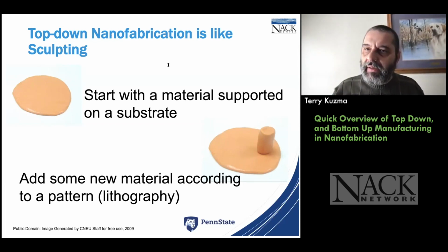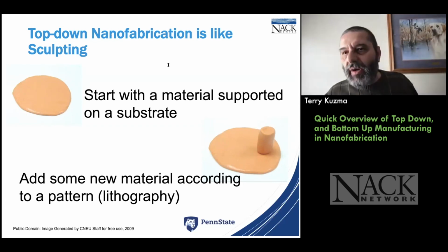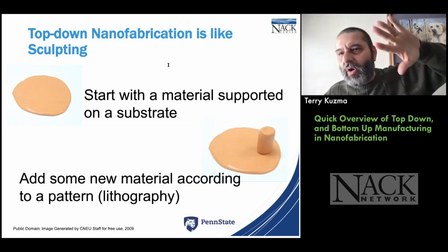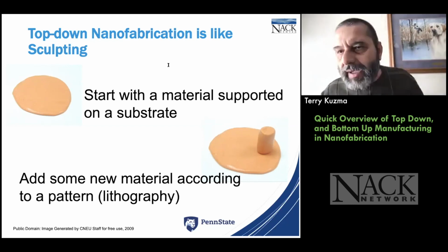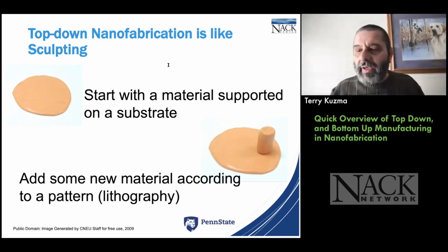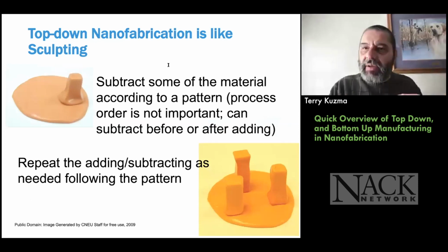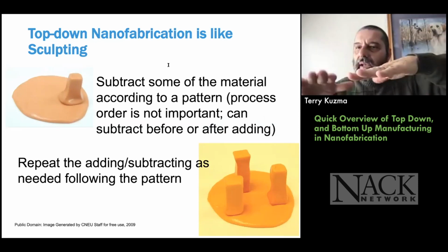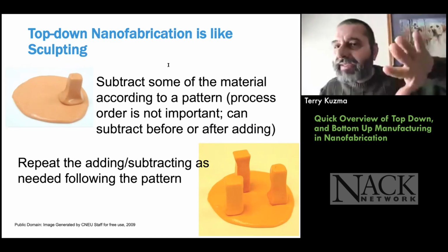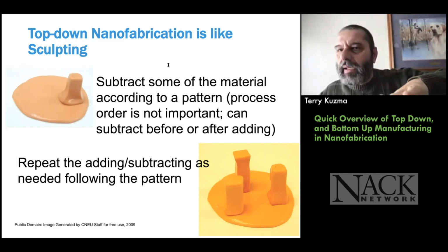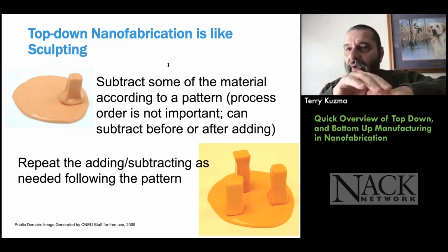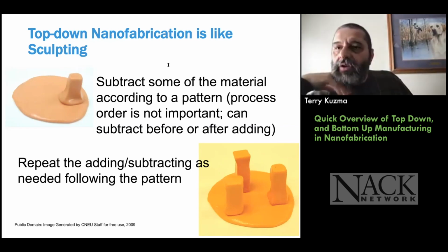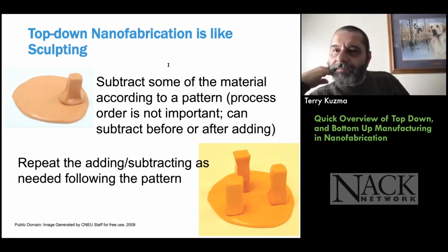Does everybody see that? And the lithography process could be thought of as your piece of cardboard that you cut your initials in. So we subtract some of the material. Certainly deposition is addition, but the areas that are exposed and other areas are protected, maybe we could dip it in something like an acid, and then the acid nibbles away at the stuff that's not protected, and the stuff that's taped off doesn't get etched away. Does everybody see that?